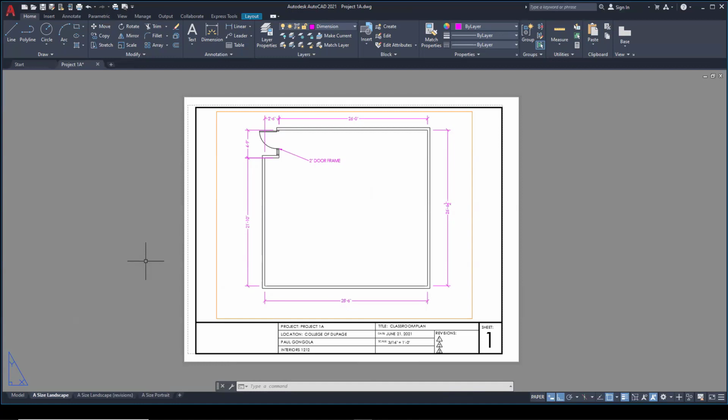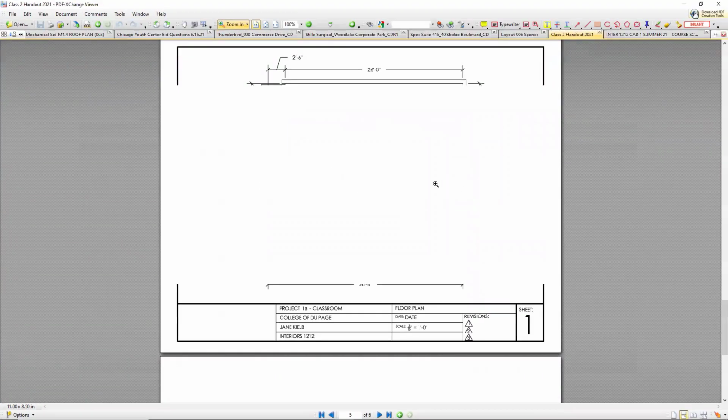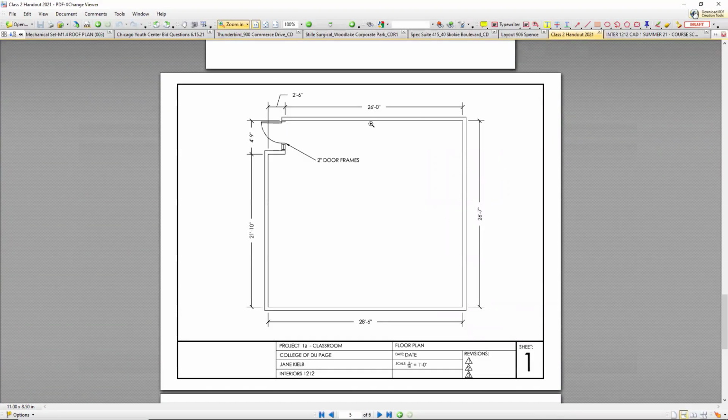All right. So your assignment for next Thursday is to duplicate this drawing here. Let me enlarge this on paper space. So draw the room accurately, put the door in and the side light, add some dimensions, and then switch over to paper space, draw a viewport, and put the dimensions in, and then modify your title block.